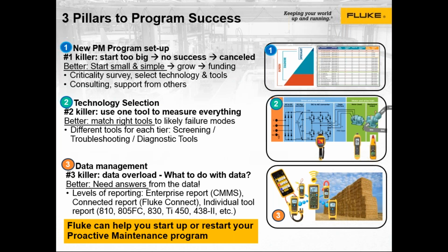You had a slide where you were talking about the importance of the equipment. So I think that how critical is that equipment if it fails to your process? I would think so. If you're trying to select between them, that would help too. Absolutely. What kind of instrument? If you don't have to worry about pumps, then that eliminates them. And if you have more electrical issues, then you focus exactly on those. Right. So think about your likely failure modes. What is causing you your biggest problems?